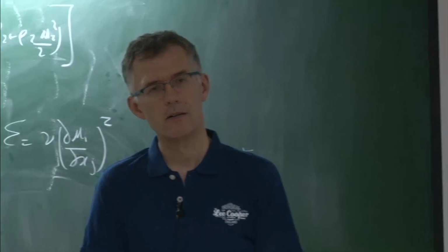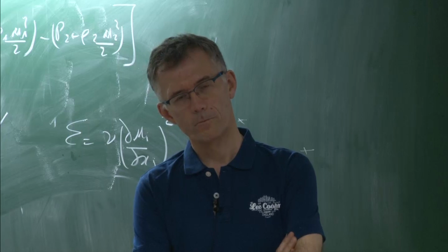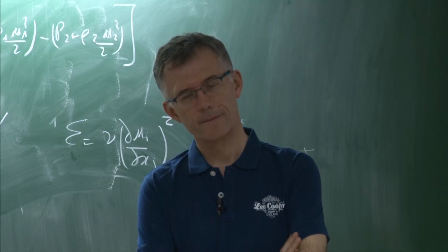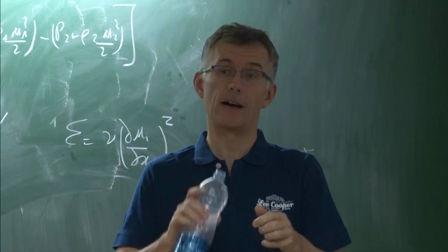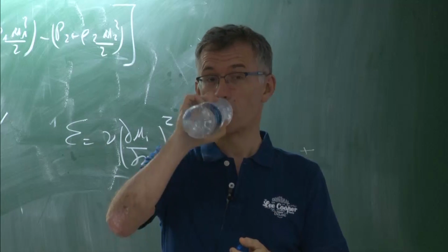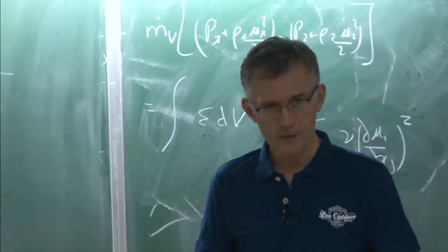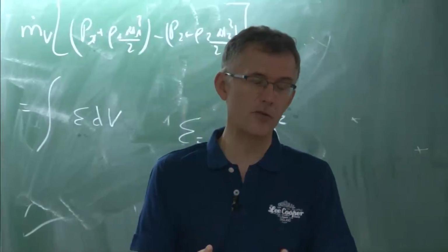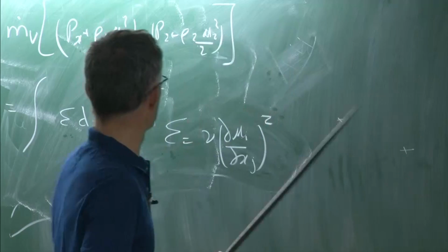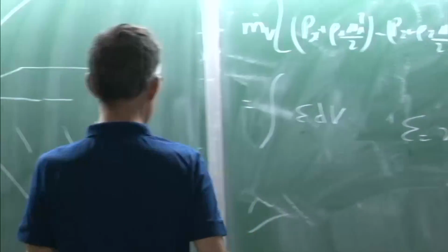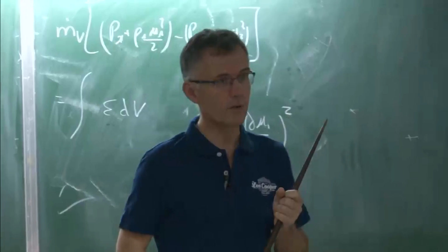So in any combustor, any geometry, when you do the meshing, it follows some critical grid size. So the grid size is maintained through the Z axis or throughout all 3 dimensions? That's the question, yeah. You don't know that when you start, okay? First, if you haven't done the computation, you need to do a first computation to see where you are.